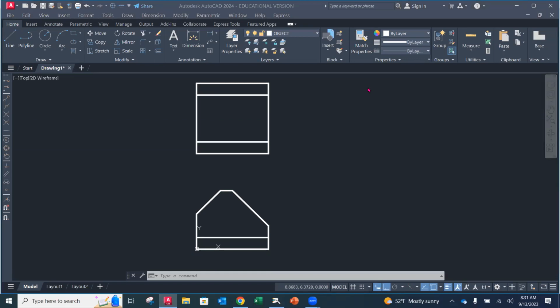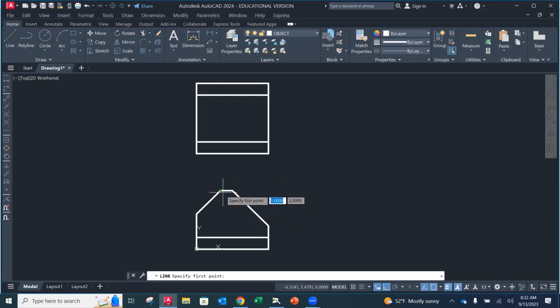All right, now let's put the little lines in right here that are going to go straight up. As we're looking in this top view, we're going to see these two edges as well. So I'm going to take my line command. I'm going to hover over, not click, hover over that endpoint, go straight up. And when it gets to the second line here, that's where it crosses over and perpendicular, not the whole width, just that inside portion. So we're going to do that same thing: line, hover over, grab it so it recognizes it, and then do the same thing.